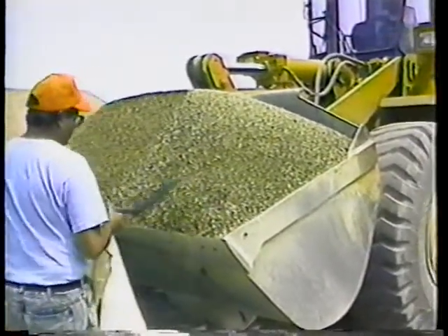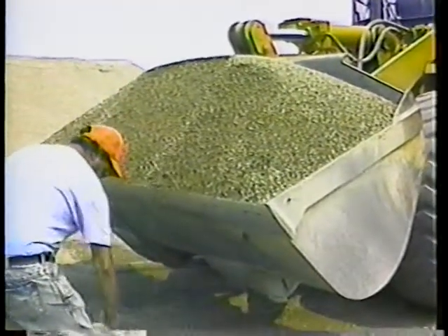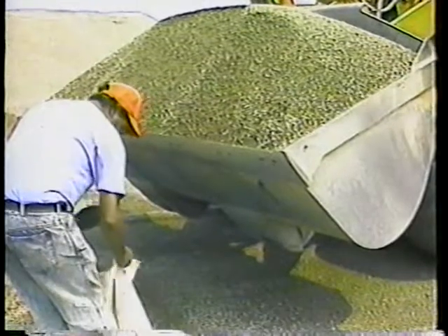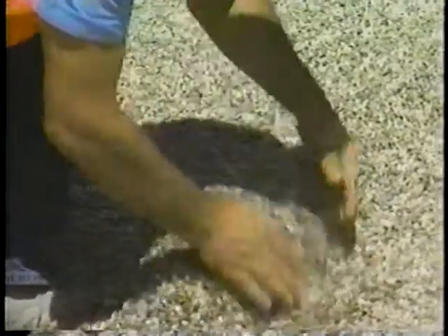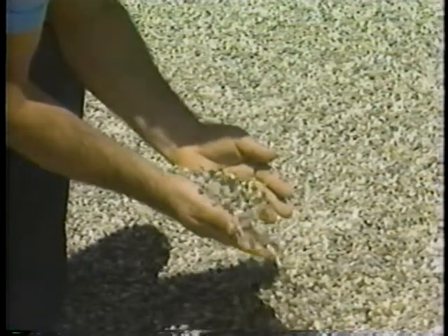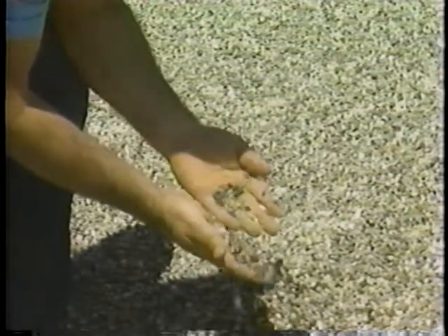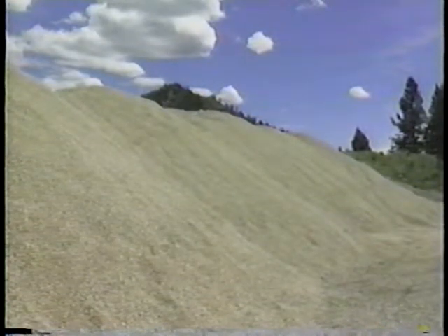Be sure the chips to be used meet your agency's specs. The size and type of aggregate depends on the number of applications to be made and the type of binder to be used. The aggregate may be gravel, crushed stone, or slag. Individual particles should be cube-shaped and as nearly of one size as possible. Graded aggregate should not be used because the smaller material would immerse completely in the binder. It's important for the aggregate to be clean. If it's coated with dust or contains clay or silt, it won't bond properly with the asphalt.